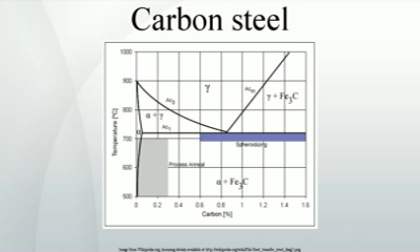Approximately 0.6 to 0.99% carbon content. Very strong, used for springs and high-strength wires. Approximately 1.0 to 2.0% carbon content. Steels that can be tempered to great hardness. Used for special purposes like non-industrial purposes, knives, axles or punches. Most steels with more than 1.2% carbon content are made using powder metallurgy. Note that steel with a carbon content above 2.14% is considered cast iron.